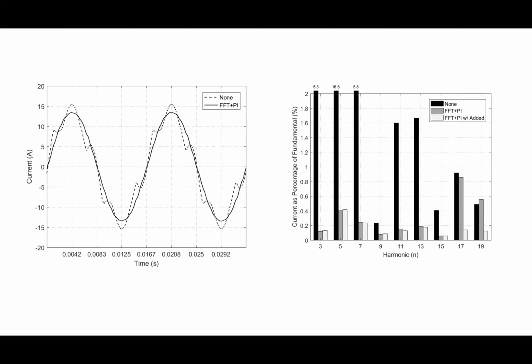Now, for the prettier looking waveform, in other words, I say it's prettier. Why do I say it's prettier? That's a very subjective term, right? Prettier because it looks more like a sine. That's what I mean by that. So it's not purely a sine. I can see, you probably can't see it as well, but I can see that it's not perfect. It should be rounder up at the top. But basically, if I looked at the prettier looking one, that's how much third harmonic it has. And here, and here, and here, and here. So much, much less. So it's much closer to what it should be.